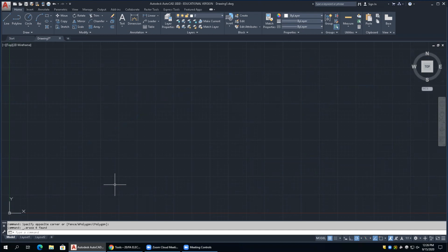So they are basically the same command. They're kind of inverses of each other, okay? So when you do an extend, I'm going to just draw a line like this. And I'm going to draw a line like this. Okay. You have to have a minimum of 2 objects when you do an extend. A minimum of 2. Now I can have more than that, but I can't just have 1.